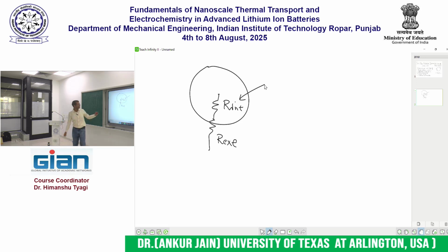I can easily cool the cell down at the bottom, sorry, on the outside. And again, these are thermal resistances, folks, not electrical. I can easily make the external resistance as small as possible by blowing a bunch of air on it, liquid cooling, all that stuff. Usually it turns out that the internal resistance of the cell becomes a problem. And that is something that I don't have much control over necessarily. I can't blow more air over it and change the thermal conductivity of the cell. The thermal conductivity of the cell is a function of what is inside of it, how it is organized, and so on. And so there is a great need for innovations in materials science.